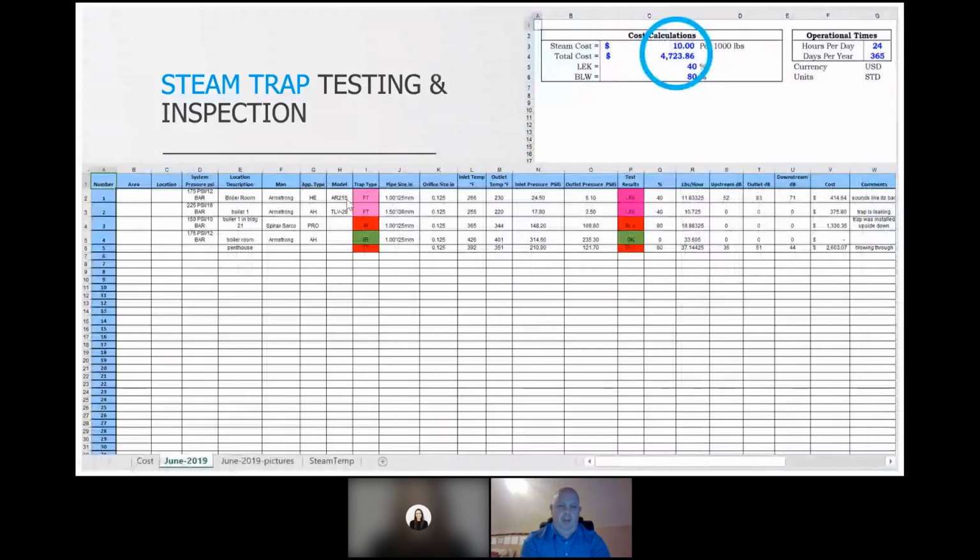So here is just a little survey that we did. We did a total of 5 steam traps. So you can see here was the type of trap. We had 2 floating thermostatics, 2 inverted buckets, and 1 thermodynamic. We determined, based off of the temperatures and our ultrasound test, that we had 2 that were leaking by, 2 that were failed open, and 1 that was okay.